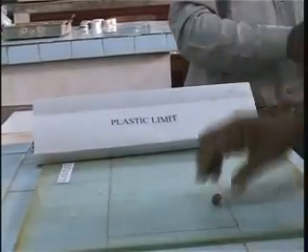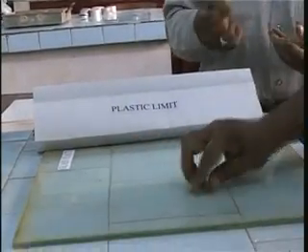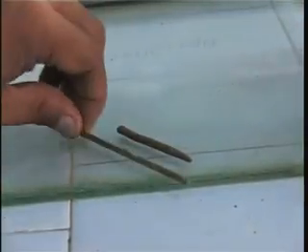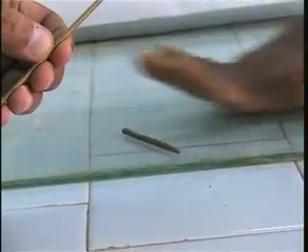That is being demonstrated by my colleague here, and this is the pad of the soil that we have here, and we just try to roll a thread by the procedure like that. And you can see that as the thread becomes finer and finer, it will have a greater likelihood of cracking. So here we have got a thread which is probably about twice as thick as the standard 3 millimeter diameter piece of wire here.